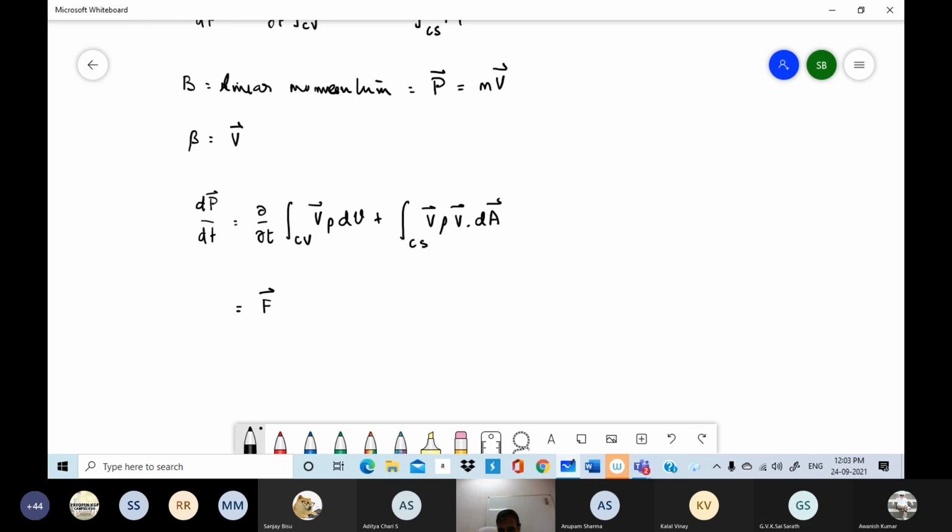If you have velocity shear, then if I consider any imaginary plane inside the fluid, the fluid on either side exerts a tangential stress, which is the viscous stress. But the tangential stress is not the only stress which viscosity can produce. Viscosity can also produce normal stresses. What is the general expression for viscous stresses? That we'll have to state, and from that determine the force on an element.